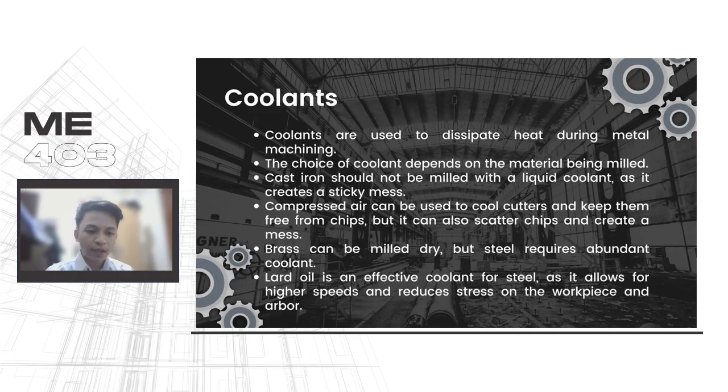Different fluids and compressed air serve to dissipate heat during metal machining, with the choice of coolant contingent on the material being worked. Cast iron, milled at typical speeds and feeds, doesn't overheat milling cutters and should not be used with a liquid coolant, as it creates a sticky mess.